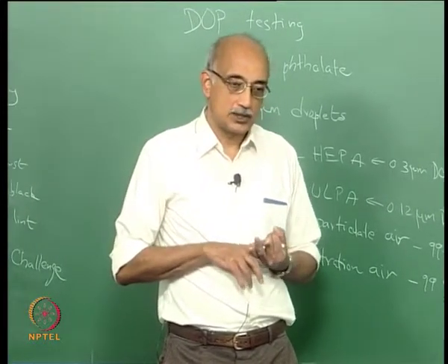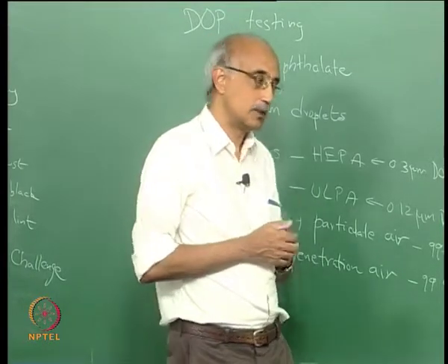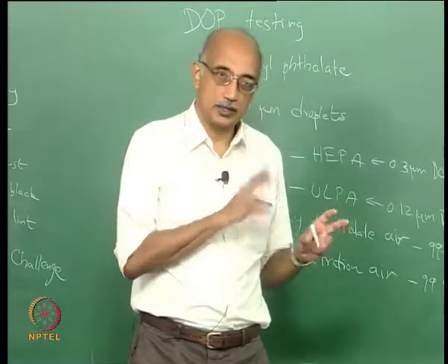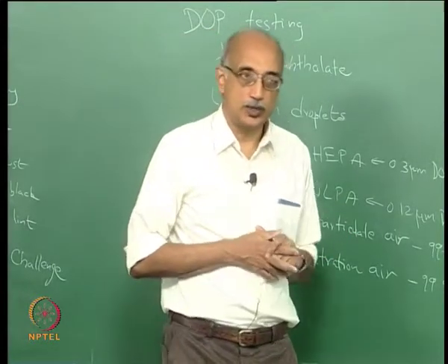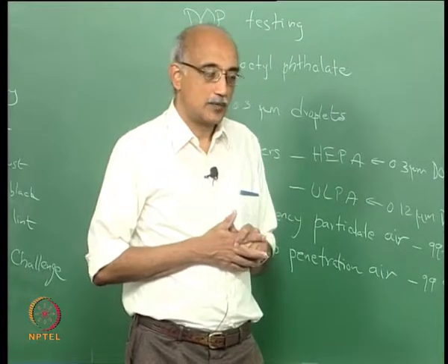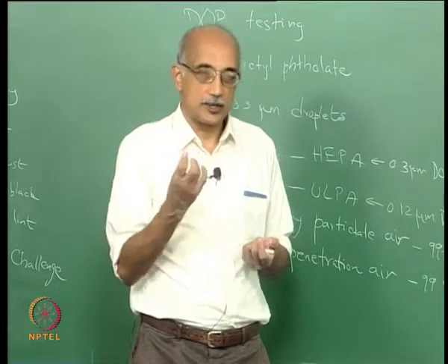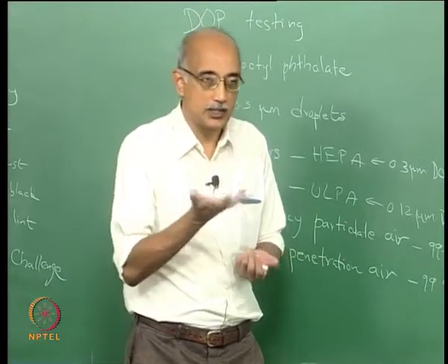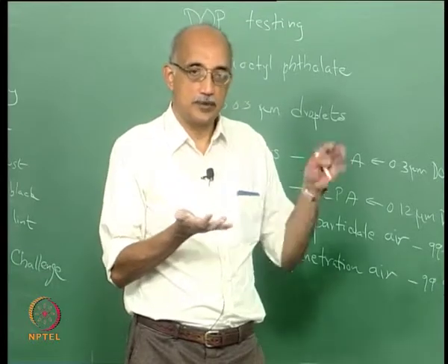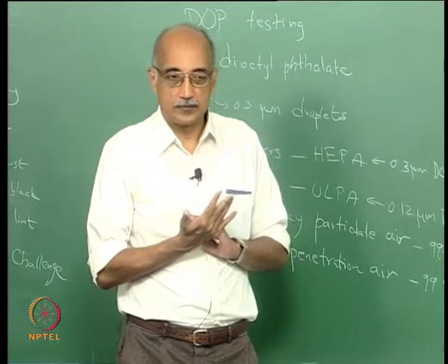Another mechanism is interception. In the case of interception, the mechanism is virtually the same for both filtration of gases and liquids. Inertial impaction, on the other hand, is very poor in liquids because a particle really cannot impact on a surface when it is suspended in liquid. It can happen very easily in a gas, but again the viscosity of the liquid layer will essentially prevent the particle from approaching the surface at high velocities.